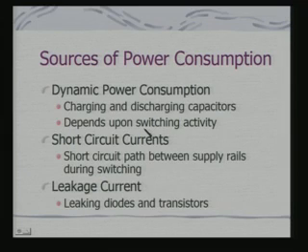What are the sources of power consumption? See, dynamic power consumption is obviously charging and discharging of capacitors, because any bit transfer with regard to your MOS and CMOS circuitry finally boils down to charging and discharging of capacitors, and this depends upon what is called the basic switching activity. In fact, this is also related to the power consumption in memory, because DRAMs are nothing but capacitances. This is also related to your interconnect power consumption, because on the transmission line also, there will be capacitances which need to be charged up.